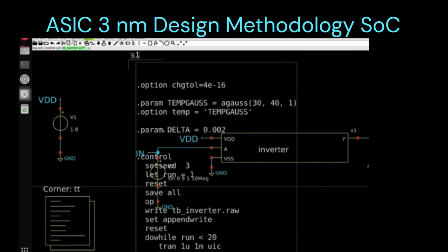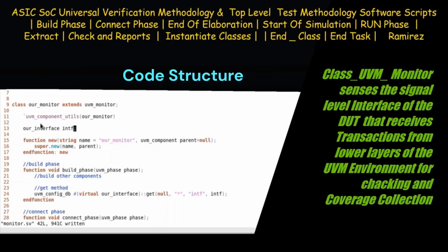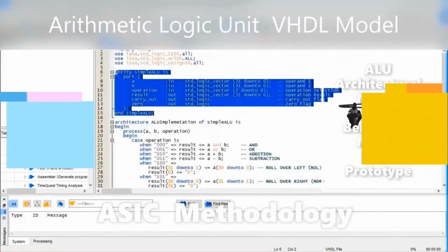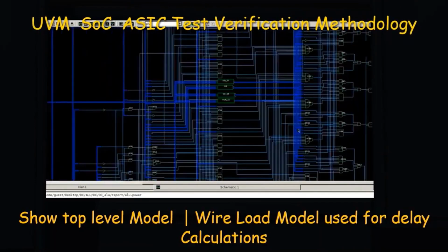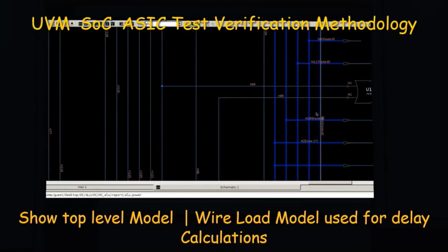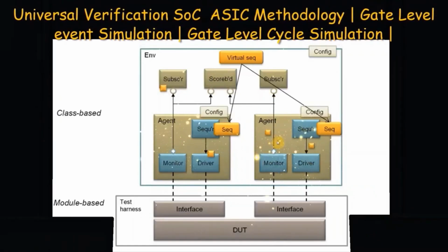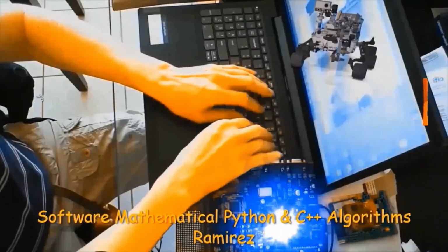In order to accomplish this task, the code has to be structured into two separate domains: an untimed HVL domain that contains the UVM environment or verification environment, and which must not contain any delays or clocks; and an HDL domain that instantiates the DUT, the device under test, and the synthesizable parts of the transactors, which can be run entirely within the box.